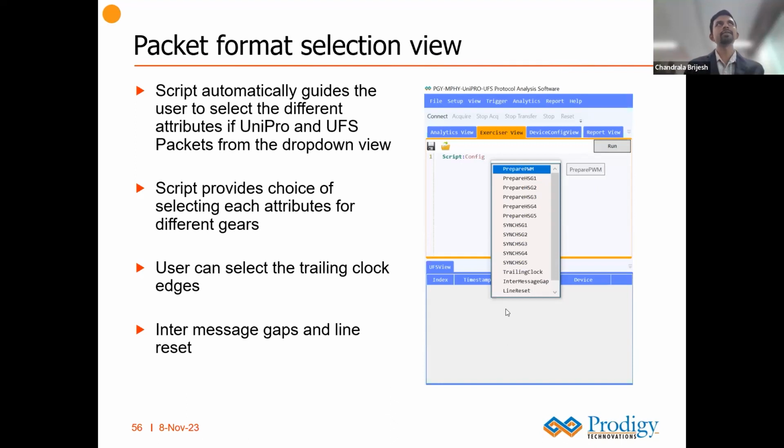Because in the old 3.1 spec, line reset was more than 3 millisecond, but in the new spec it is around 300 microsecond. So we do support all kinds of line reset, and you can test, okay, what is the minimum and maximum line reset time required.